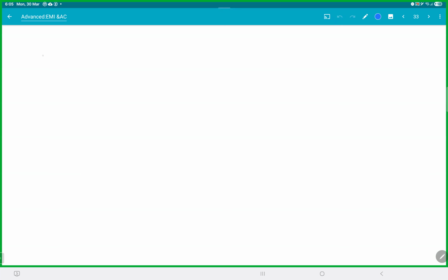If you have a function like, let's say, v is equal to v naught sine omega t, where v naught is the peak value, we can write v bar. So I am converting a sine function into the vector, which is v naught angle 0. This v naught represents the amplitude and this 0 represents the phase angle. To put it simply, if someone gives you v is equal to 10 sine (omega t plus 60 degrees), the phasor way of writing this is v bar is equal to 10 angle 60 degrees.